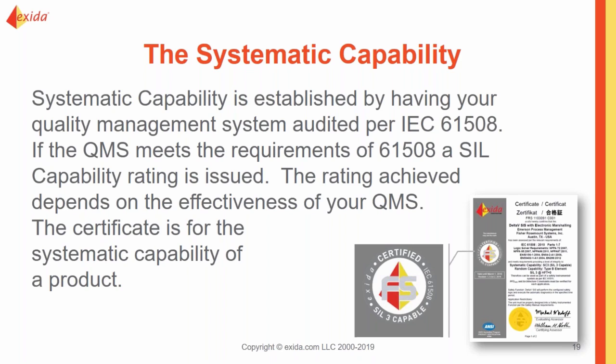So, if you have a SIL 2 ball valve that you bought, it can go into a SIL 2 application, a SIL 1 application, a SIL nothing application, but it will never be okay to go into a SIL 3 application. And I don't care how many of those you stick in. You can put 4 of those SIL 2 valves in to cover one SIL 3. It will not count. So that SIL capability rating is a limiting factor on all of the certificates.